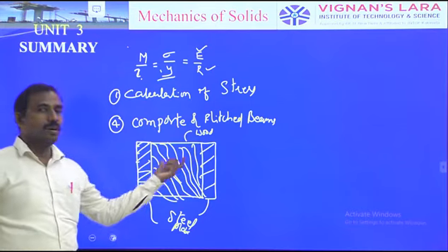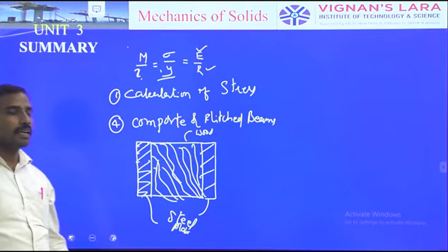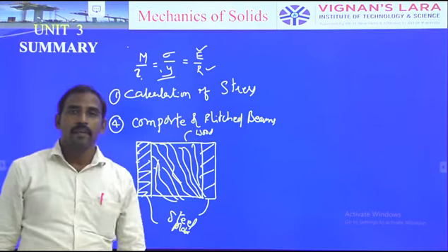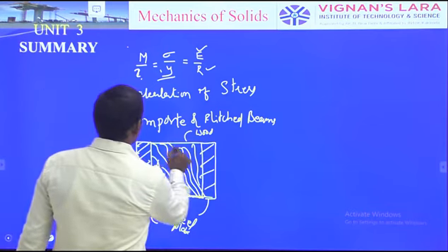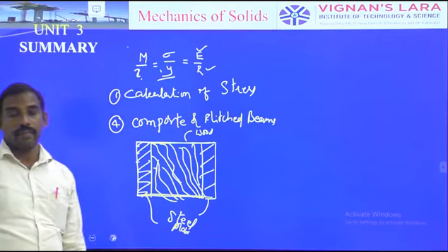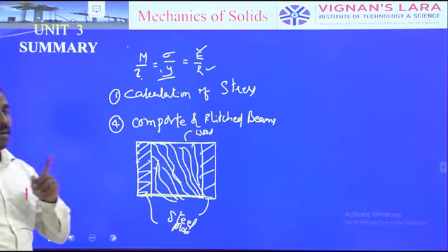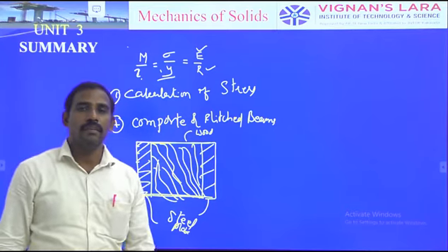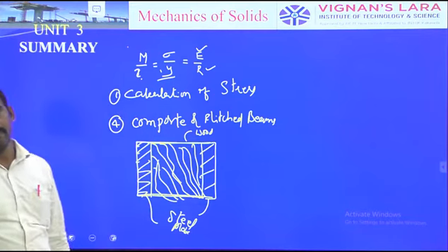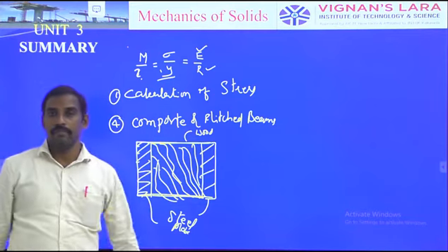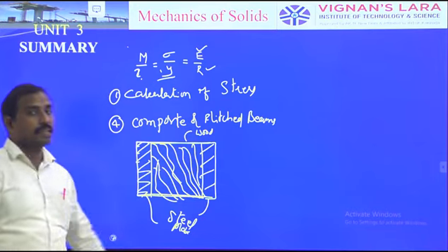So simply it is the combination of two different materials like wood and steel, rigidly fixed at both the ends. Here we have to remember only one point: the strain is the same in both the materials whenever it is subjected to a transverse load.